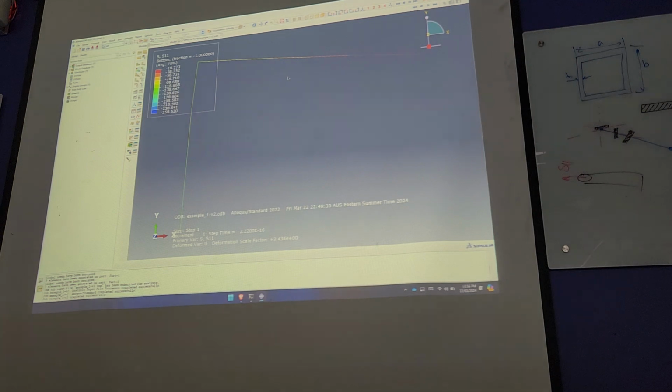Then thickness I'll put uniform thickness, then assign any thickness. Thickness must be less than half. So 0.005, maybe just put 0.01, at least 10 mm thick. Okay, then the stiffness and all this is okay.